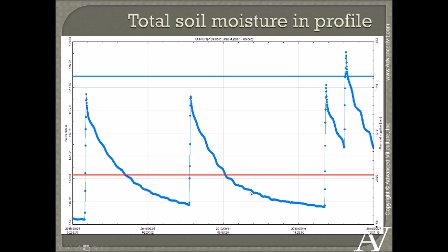And in this case, we're kind of looking at re-irrigating at a stress level. But if we put that re-irrigation point, which is this red line, I'm just being hypothetical here. Right now I'm showing this red line at the point where this readily available moisture goes away and we start getting into the more stressed level. We can put that line anywhere as a reference line to where we want to irrigate again.